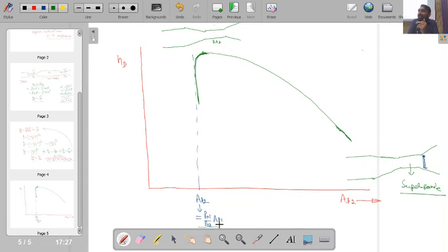Okay. However, if I keep the throat area very large, then I will have a decrease in efficiency. Okay. But this particular area of throat, whatever we are calculating, is calculated based on the assumption that my wind tunnel is already in operation and I am able to achieve a Mach number of ME. Okay. But here one operational issue comes. The operational issue is when you are going to just start the flow. Okay. So what will be happening?